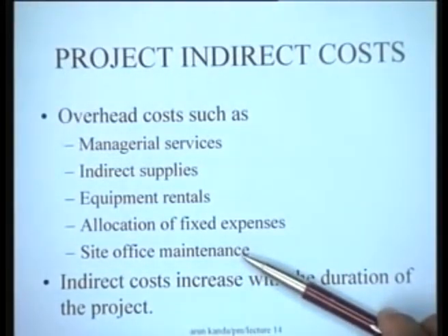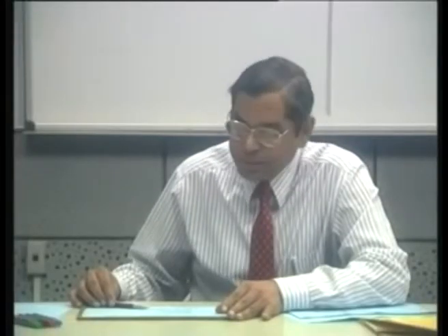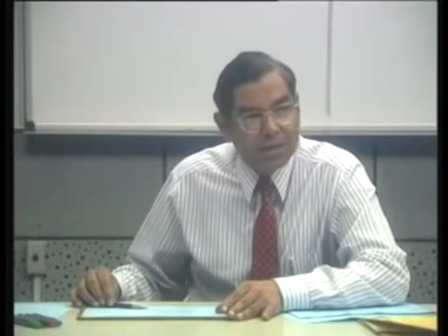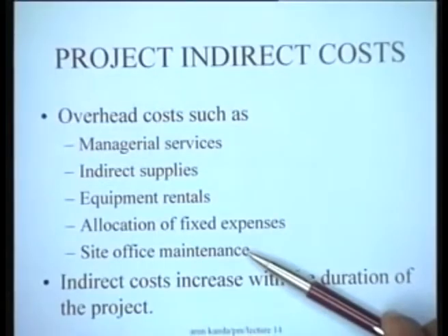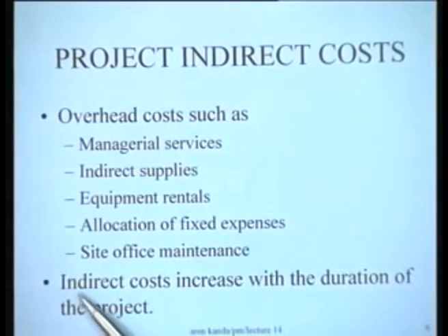As long as the project is in progress, you would have to maintain a site office, and the costs associated with that site office are dependent upon factors like how long the project is in operation, because you will have a per day cost of operating the site office, and therefore you would have these kinds of indirect costs. The important thing to note is that all the indirect costs increase with the duration of the project. Typically, the longer the duration of the project, the more you have to maintain the site offices, so there is a per day cost associated with that.